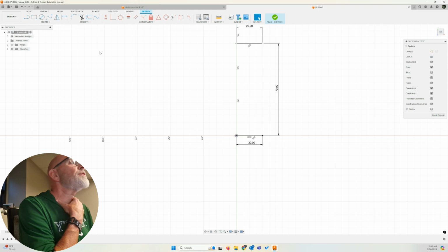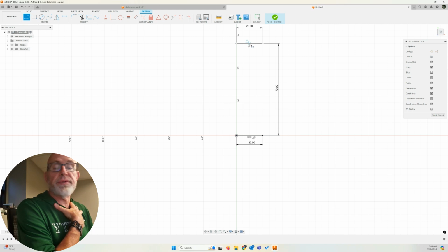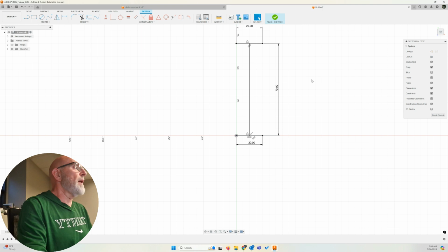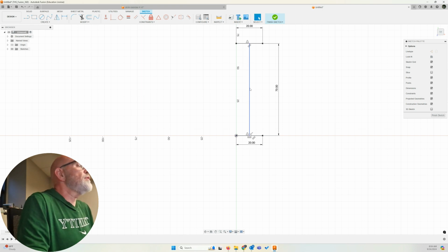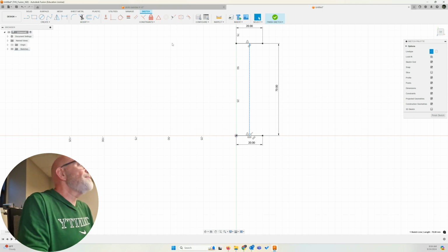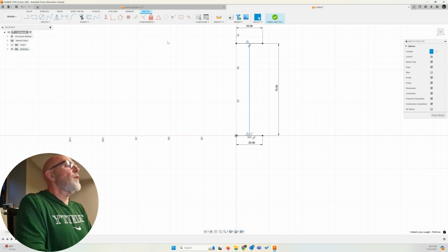All right, let's create our vertical construction line from the midpoints of our two lines we've drawn. There's the first midpoint, so I'm going to click, come straight down 90 degrees. Yep, click, and I've got midpoint constraints on both ends of my line. Very good. Let's change it to construction. Select the line, keyboard, the key X, toggle it to construction. There we go.